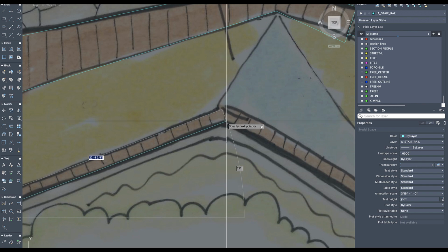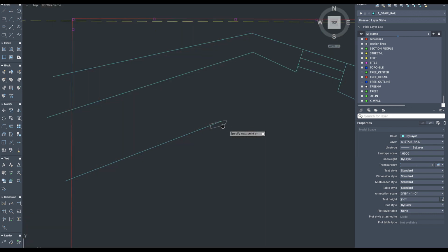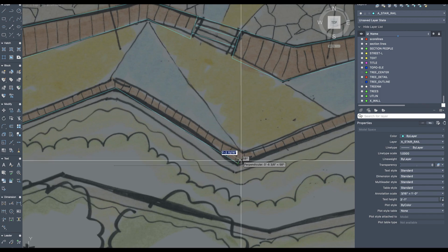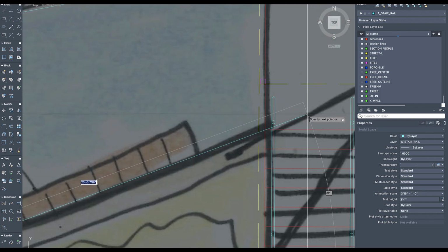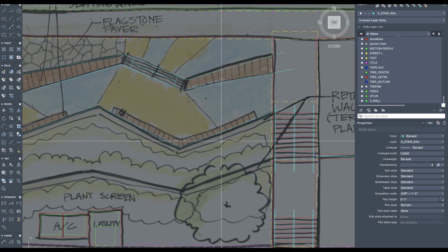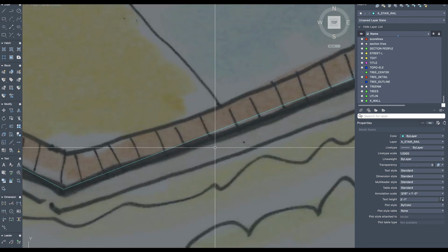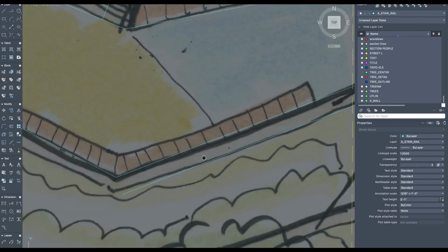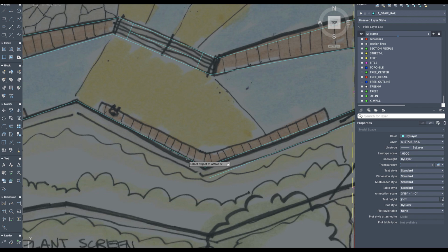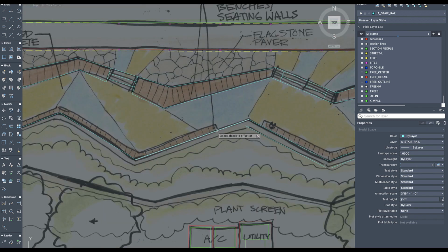It's going to be a little more traditional in the sense that the wall thickness here, that retaining wall, is going to be a consistent offset. So we're going to create this line work in here. Bring it over there and figure out what the depth of this wall is going to be. We don't exactly know what material. It's probably going to be concrete with a rebar cage. In that case, we might say we're looking upwards of 18 inches thick. And we can just offset this 18 inches at all of these spots.